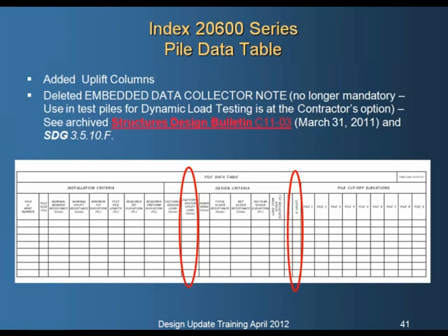You can use the standard table. We've also deleted the embedded data collector note. It's no longer mandatory. There's a bulletin that came out last year on that. The contractor still has the option to use the EDC as part of the dynamic load testing requirement, but we no longer have to mandate that on every project. Refer to the bulletin for more information on that, or actually the information is now being rolled into the structures design guidelines under 3510.F.